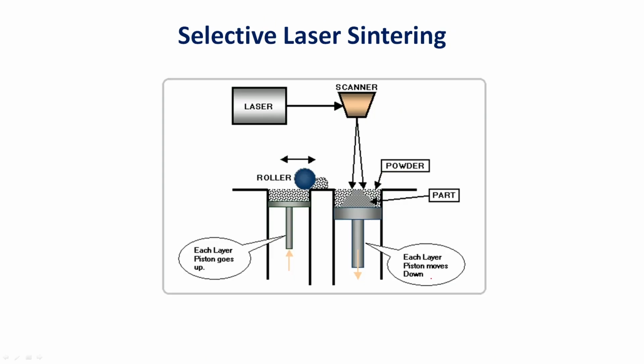Well, one can also use selective laser sintering. You can put powders there and then use a scanning laser. You can partially melt, or incipient melting of the powder particles can happen, and they will then join together and form a nice bond, and then you can form a part. Okay. So there are many techniques available for sintering.